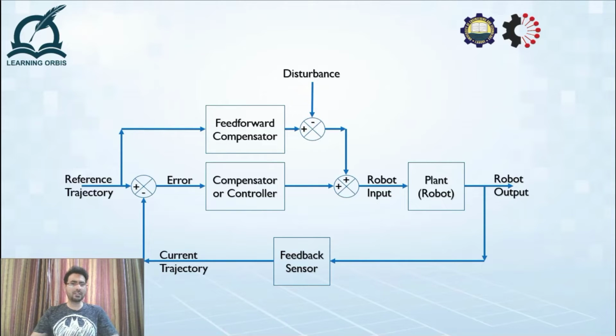The drawback of this was that the PID or PD controller must work a lot. We had to carefully tune the parameters through an optimization routine, and then the controller was able to move the robot to a desired set point. Furthermore, as per my suggestion, if you have tried to use the same PID tuned controller with a varying trajectory, then you must have seen that the controller was unable to follow the trajectory perfectly. I'll reiterate this point when we get to the simulation part later in this video.